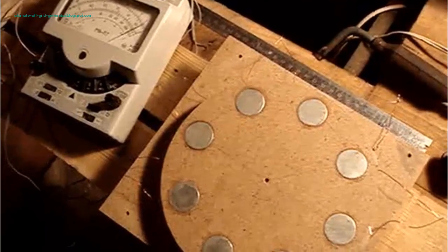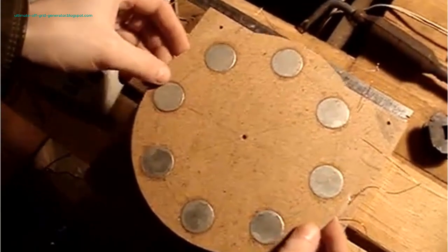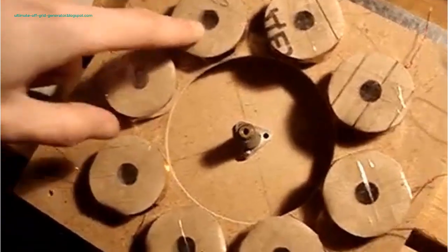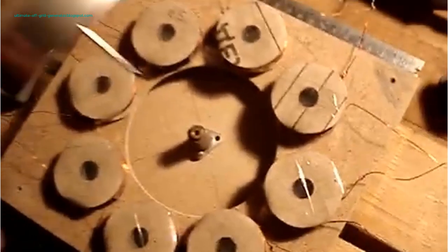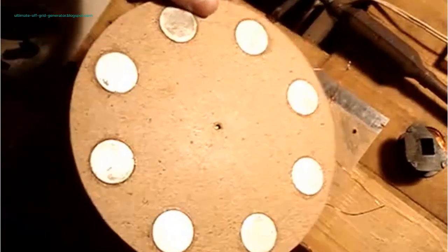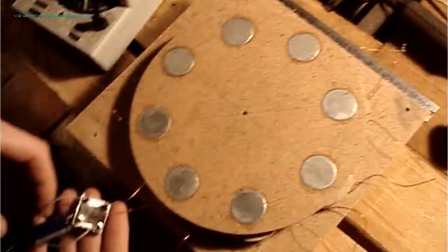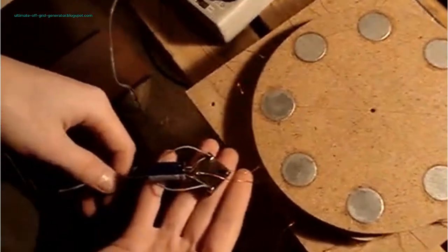As the magnet gets closer, the Hall IC starts to activate. However, since the voltage at the transistor's B, base pin, is still higher than at the E, emitter pin, the transistor remains off and the coil circuit stays open. When the magnet reaches the exact center of the iron core and the coil wrapped around it, the voltage at the B pin is still higher than at the E pin, keeping the transistor off.